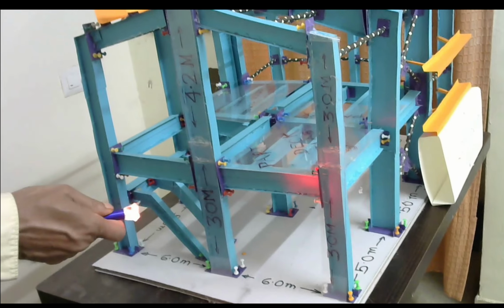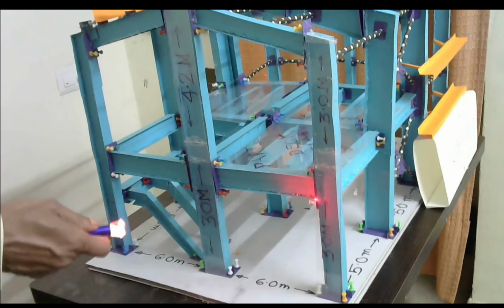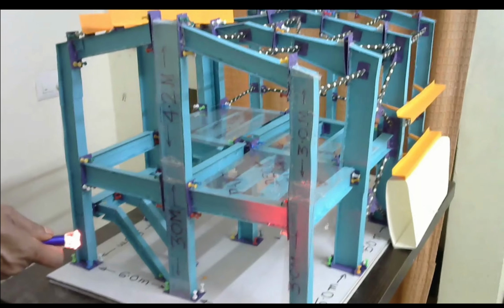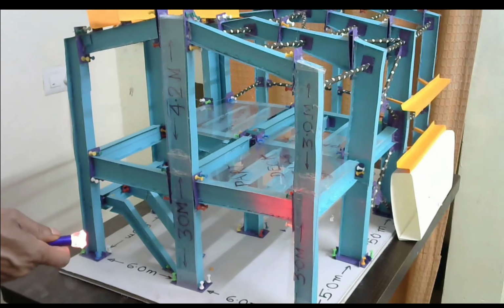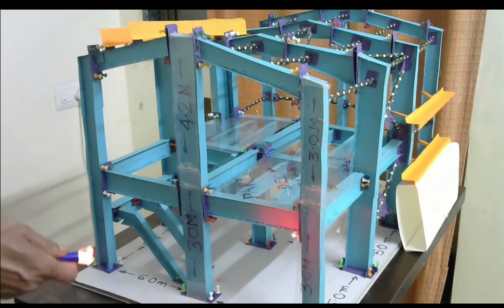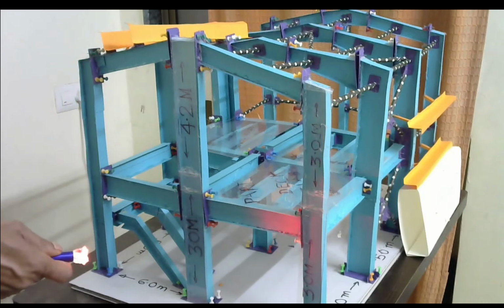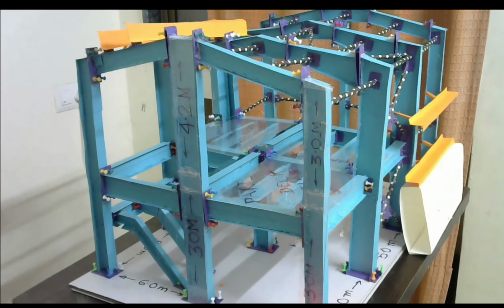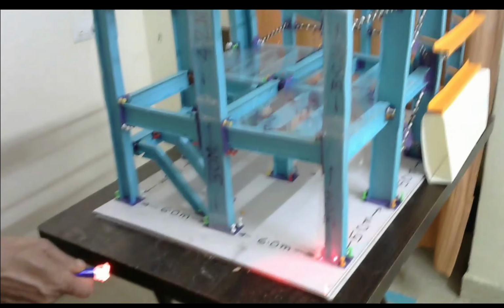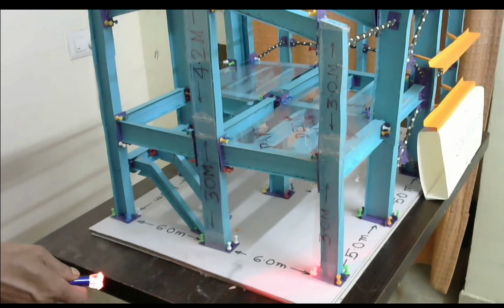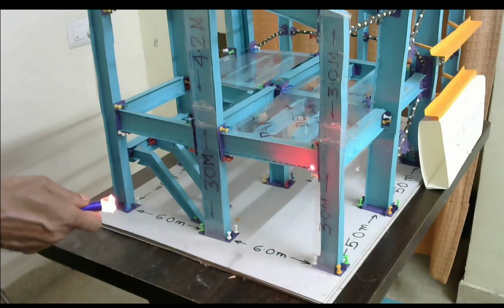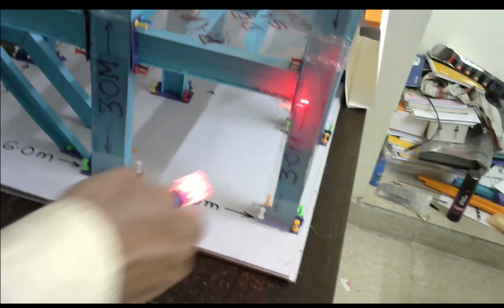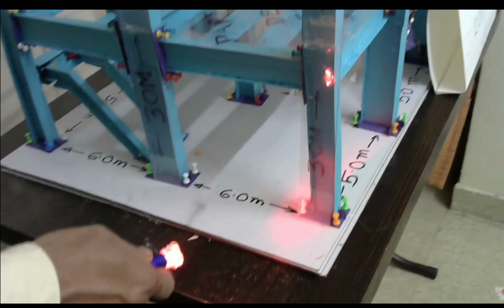This is actually an 8 bolt connection, but here we have provided 4 bolts because the model is small, so 8 bolts could not be accommodated. So this is a moment connection, and it will restrain this column from twisting. From the base plate, the base is fixed. This point is fixed. There will be a stiffener plate along this point, though in this model we do not have a stiffener plate. So in this case, the flanges are also restrained.